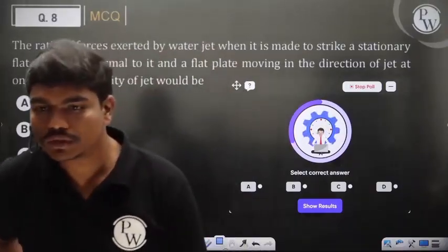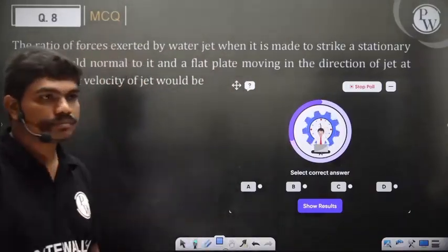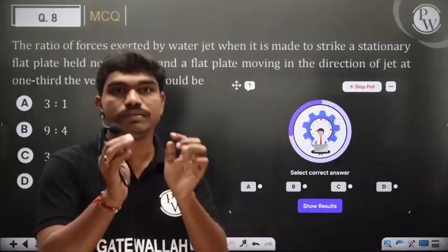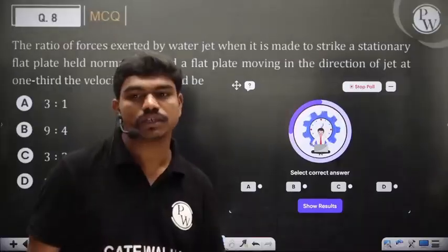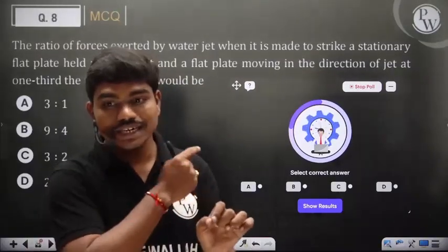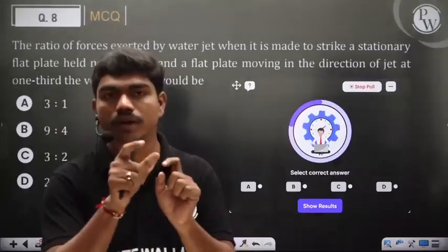What is the significance of that speed term? That term denotes the power and head combination, which should be made equal between the model and the prototype. If you are picking a turbine for modeling, we make sure this NST term should be made equal between the model and prototype.